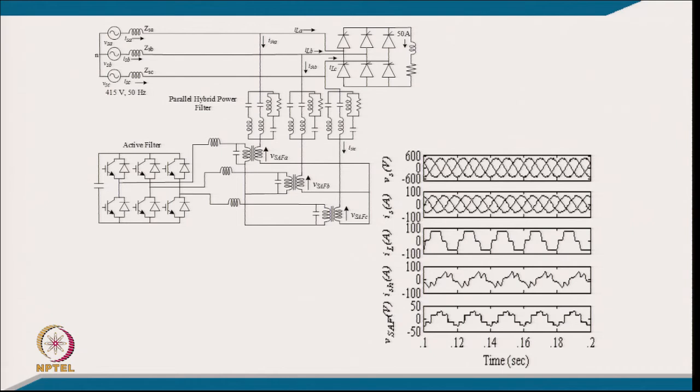So, this is typically the configuration which we discussed earlier: we have a current fed load, and a passive filter to provide the reactive power, and all the harmonics we have to suck with the help of this series active filter. The series active filter is supposed to avoid the resonance and generate a harmonic voltage of variable value, so that the passive filter sinks the harmonic current that is typically drawn by the load. Indirectly we can control this series active filter so that the supply currents are balanced sinusoidal and harmonics are forced into the passive filter. We can control it in an indirect manner.